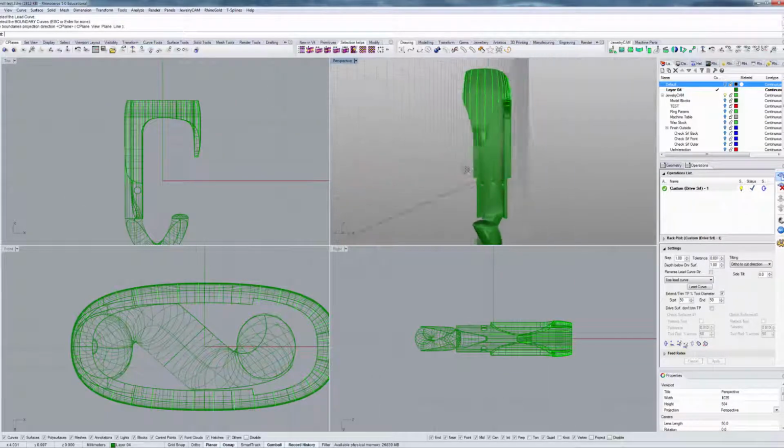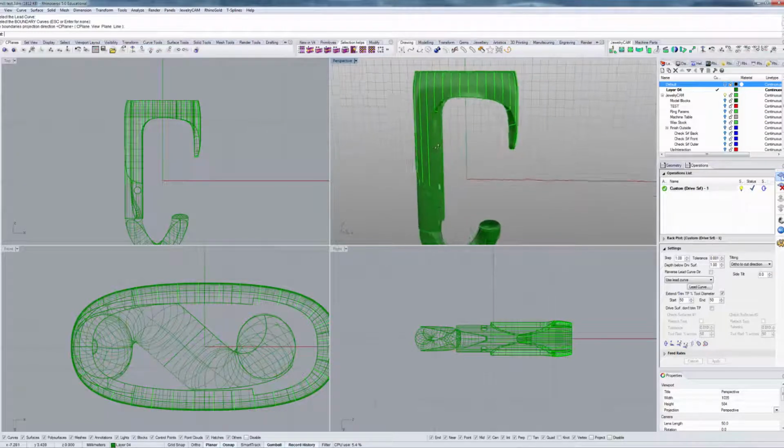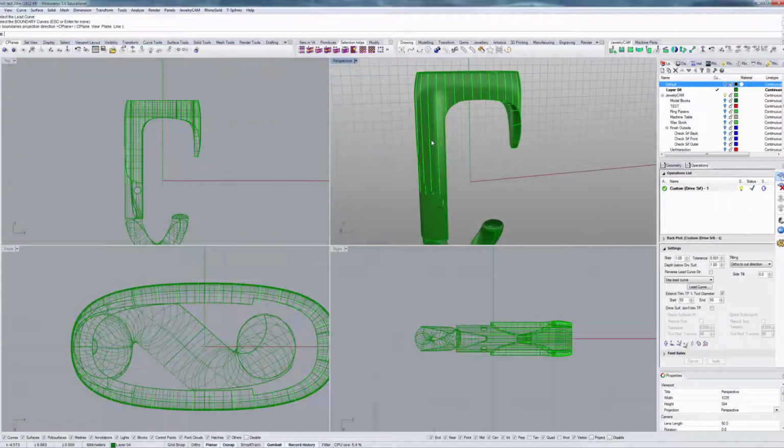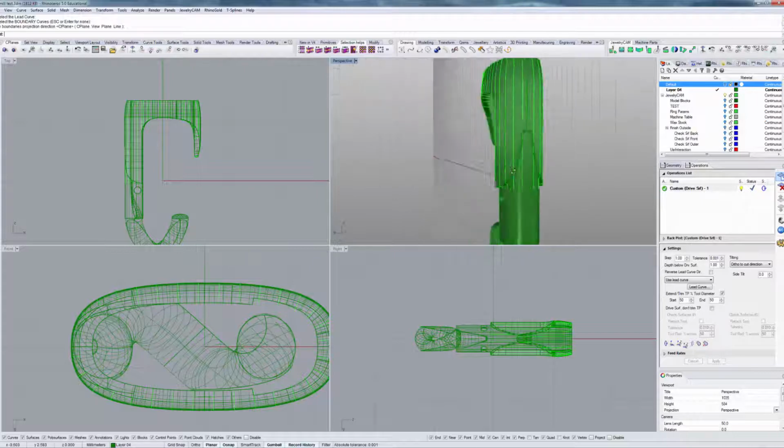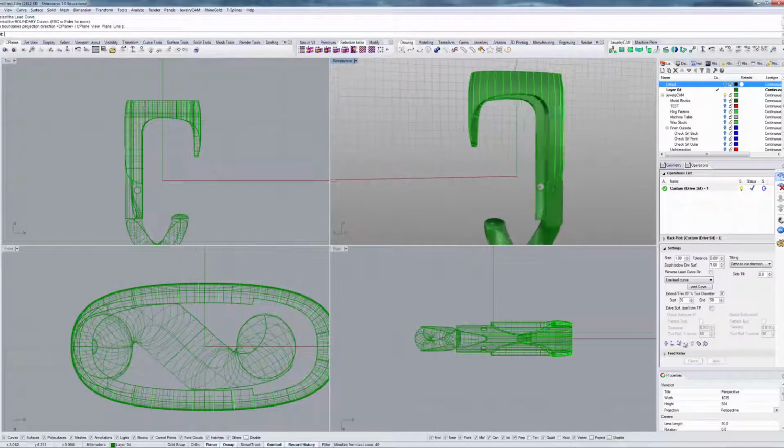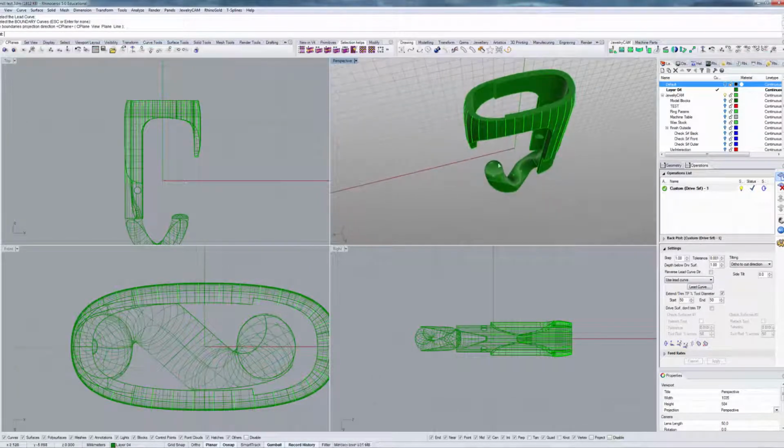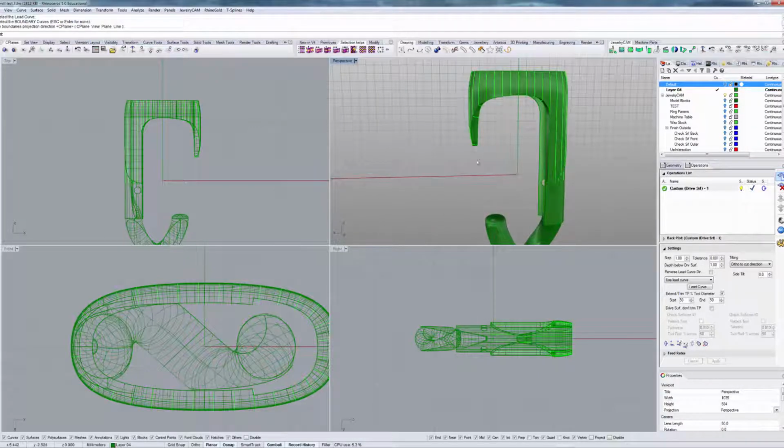We see that our tool bit will go around this whole model, well, the portion that was covered by a drive surface, and will make cuts that are consistent with our lead curve. So if our lead curve went this way, then the cuts will be perpendicular to it. Likewise, if we had a lead curve going this way, the cuts would be perpendicular to it that way.